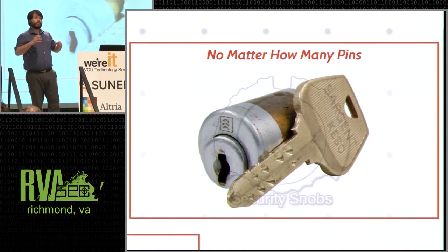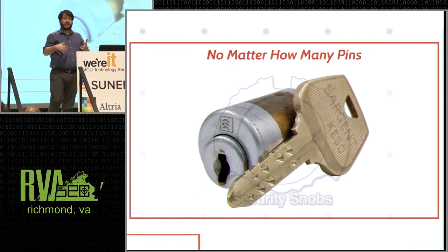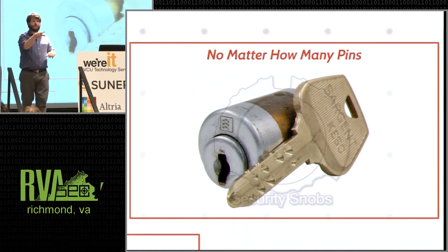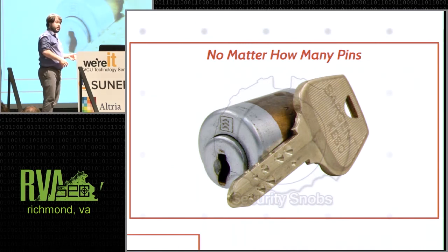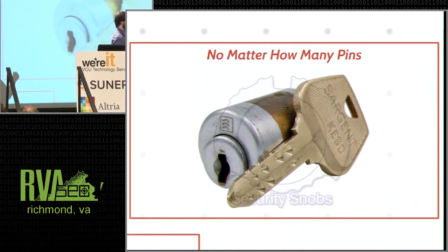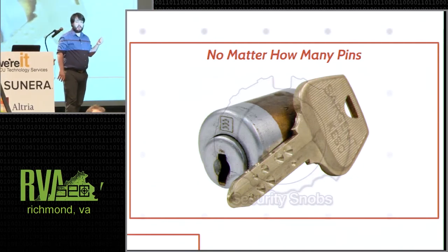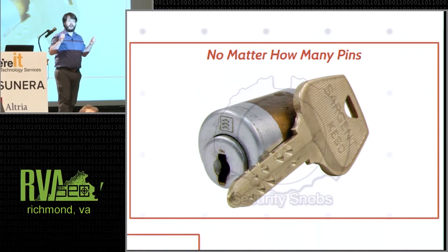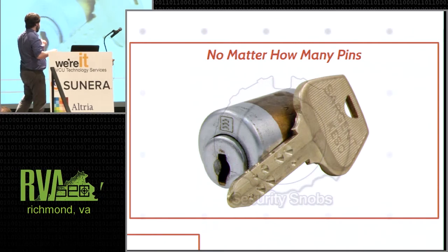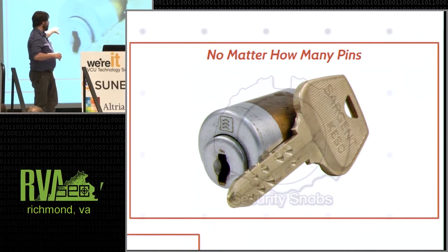Okay, but as Sergeant Queso will tell you, no matter how many pins you have, it's still relatively easy to duplicate your key. Potentially, even when they're dimple keys, to reproduce them from a visual or a photographic inspection. So Queso, much like those early Egyptians, Mesopotamians, Turks, realized that they could have variable pin spacing. So when you look at a Queso key, not every pin will be perfectly even. They have a ton of chambers, but not every chamber is filled, literally.